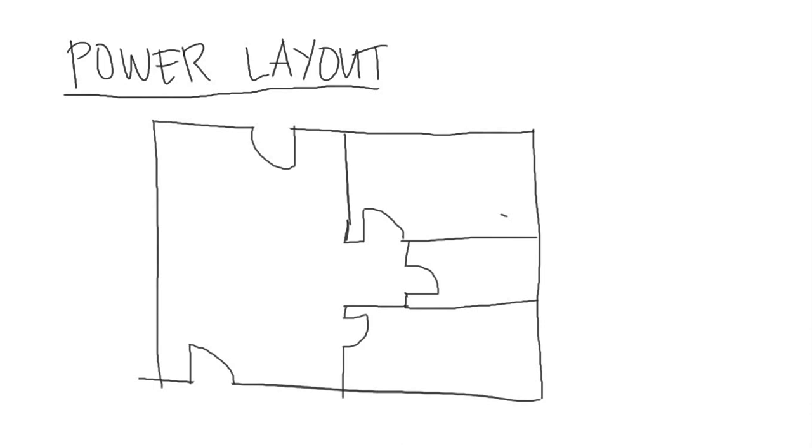Ref. So it should be indicated. If this room has one aircon, it should have a special outlet for aircon. So a circle with a triangle inside, and then you'll put ACU here, meaning air conditioning unit. There will be two air conditioning units here, so there will be two special outlets for aircon, ACU.